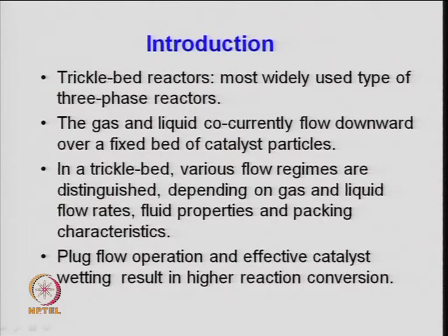So, since it is mainly governed by mass transfer operation, when you have mass transfer operation, you need a definite kind of packing, structured packing, right. So, just like in a packed tower, you look at different kinds of packing materials, because the surface area per unit volume is very important, and that will depend on the type of the gas which is to be absorbed in the liquid. So, a packed bed absorption column, which is a mass transfer phenomenon, but in a trickle bed reactor also the gas and liquid.